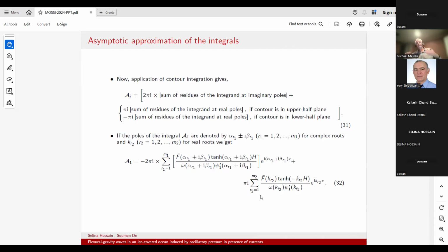Okay, yeah, I'm just saying because normally there's a causality that pushes the pole off the real axis. Normally for that we need some dissipation, like Tatiana explained, a viscoelastic plate or poroelastic plate. In those cases it is okay. Otherwise, you can get waves coming from infinity or something funny like that. You get non-causal disturbances coming from the real poles at infinity into your problem. It's good to put some dissipation so the poles are not real but close to the real axis. Now you and me are talking, but are there any more questions for